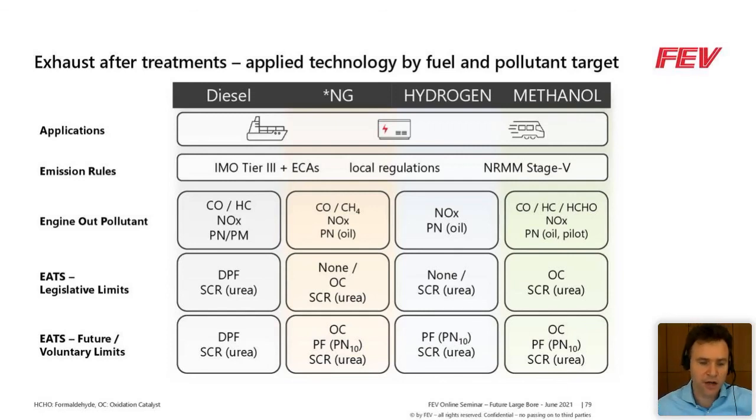And in future, if the particulate number will be limited, these engines, for example hydrogen or methanol, don't have any issue with soot. But of course the particulate number will play a role, because these engines still need oil for lubrication. So the oil can for sure generate particulates, and the particulate number, as already today, has a quite strong focus and most likely in the future will also be regulated. So we could also think that in future a particulate filter also has to be used for those engines, but of course with, I would say, less complexity compared to today's particulate filters.